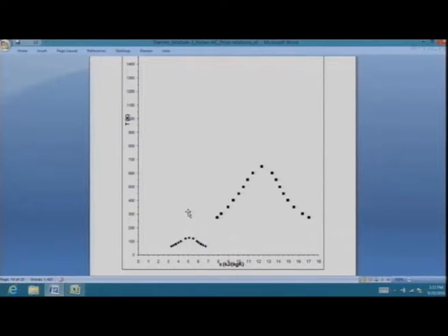So reduced temperature, the way we just defined a few minutes back, for ambient condition for nitrogen will be about 2. And so look, we are far away, and so we presume that air around us, and for all purposes of calculations and analysis, we treat air, or the nitrogen part of air, as an ideal gas. Do the same thing for oxygen. The curve will be lower than this slightly, equally good for oxygen to be treated as an ideal gas at